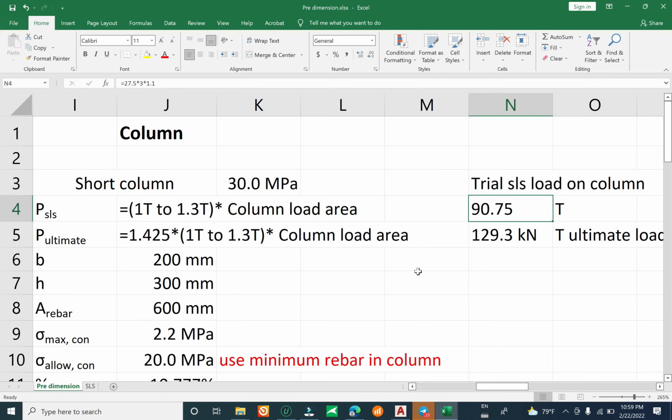Now we have the 3 load values, so you can take this value to calculate the bearing capacity of your soils. You can just get the column load, and to predict your foundation you can select a shallow foundation or deep foundation. It is very important to know the column load.